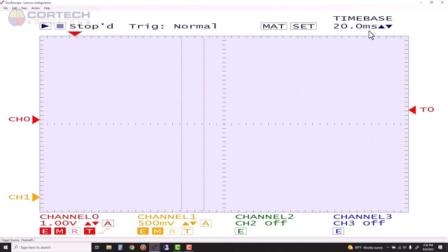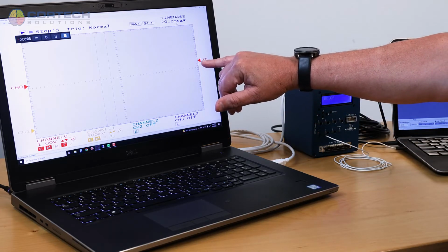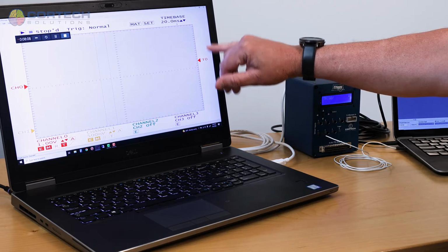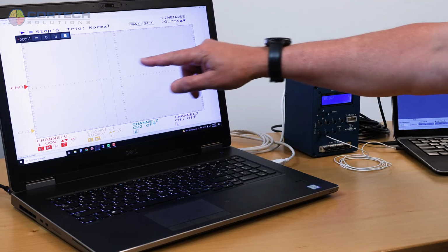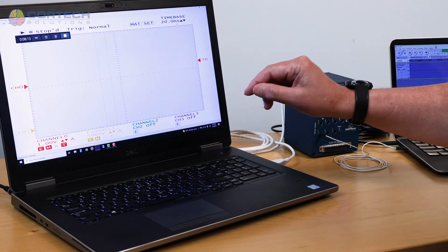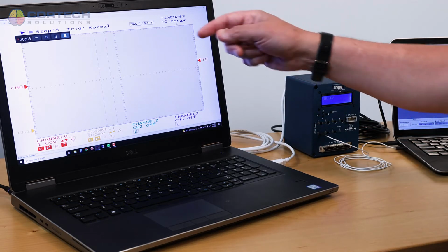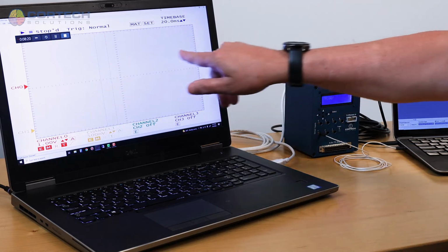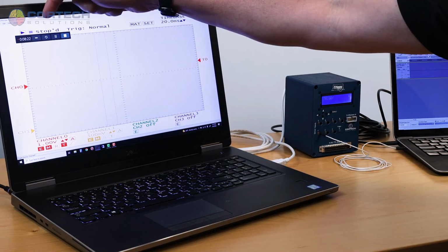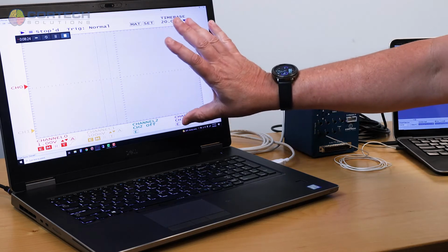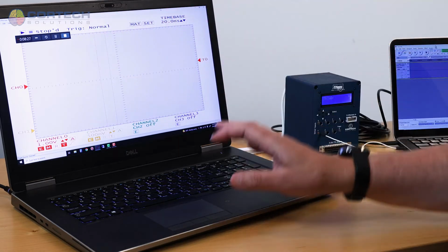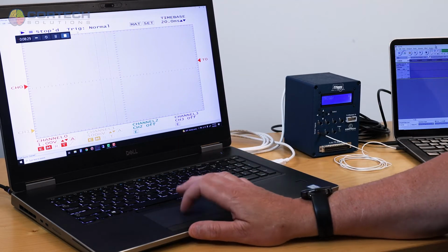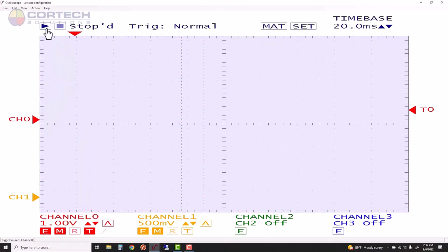Another feature is this trigger threshold. That's important to note. We'll use that to determine where on the signal to catch events that are exceeding the threshold. And then when it triggers, you'll see the signal in this window with a vertical cursor that we can move in order to move the signal to the left or to the right of the window. So I'll just hit start, it's like a play button, a right facing arrow.